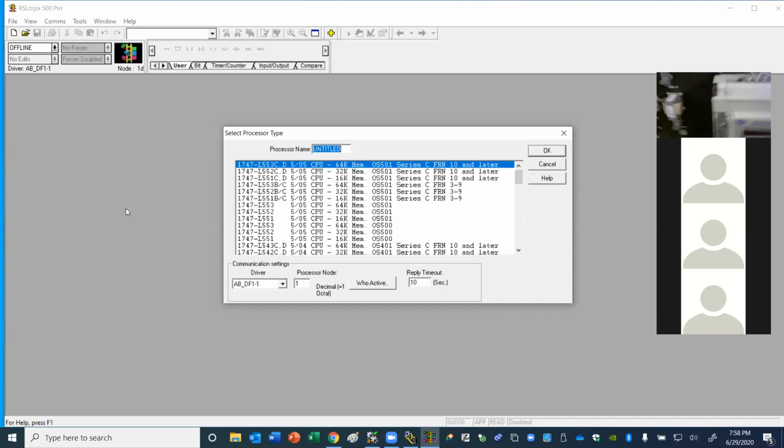So do you see the PLC now? Yes, sir. You see that little catch thing right there? You pull that out like that. That's a lock device. And then we're going to slide the whole front out. The CPU is actually a part. The CPU can come out of that main frame there.